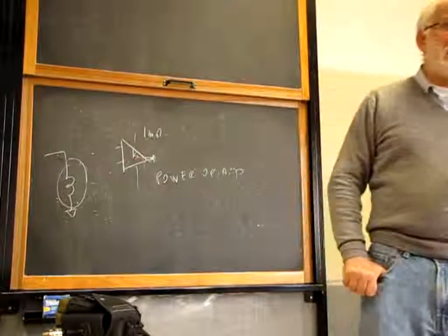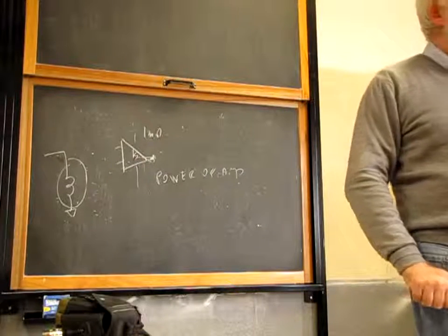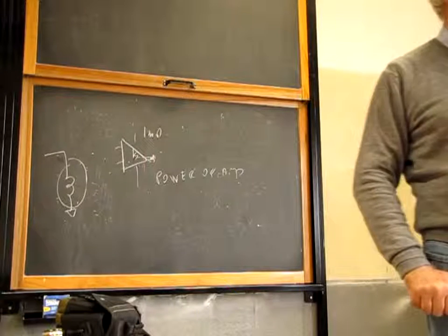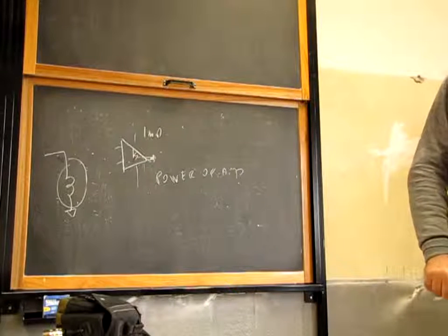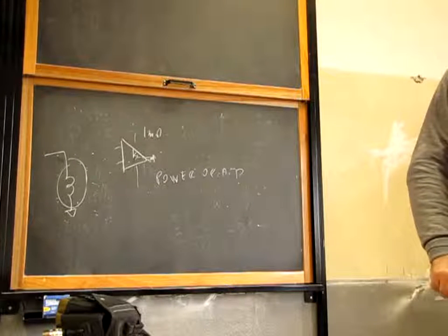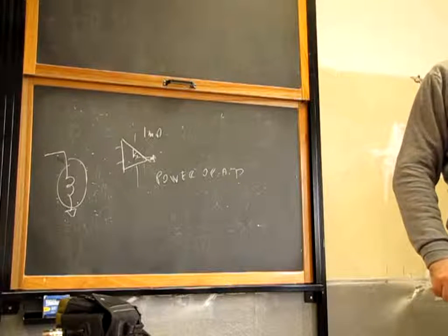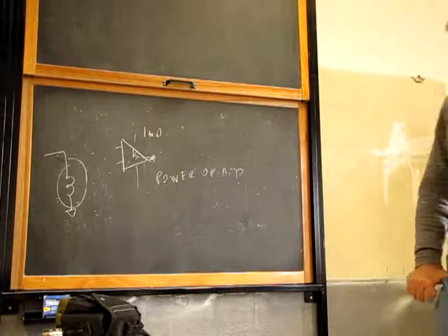You can use synthesized inductors in filters. Filters are okay because filters are small signal. The current flowing through filters is very minuscule, microamps, milliamps maximum, so who cares? An op-amp is fine. But in a power supply, all our components can carry very high currents.